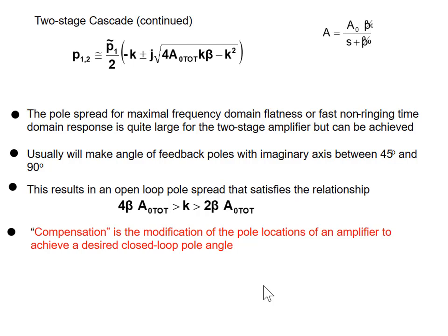Yes? But how easy is defining beta in your design? Real easy. The number polynomial is always 1 plus A beta. So the system designers will dictate what beta is for your circuit. Then the circuit designers have to build a circuit that works with that value of beta. Make sense? Yes? Have we related K to physical or the practical parameters of our circuit design yet? Not yet. But it's easy to do. We're going to see that K is primarily determined by the size of a capacitor. And that capacitor isn't in our circuit yet.